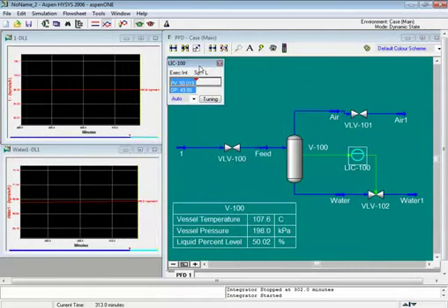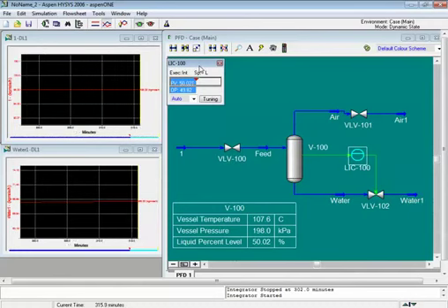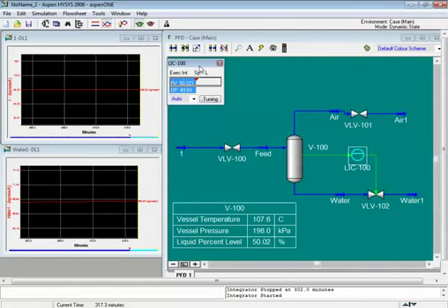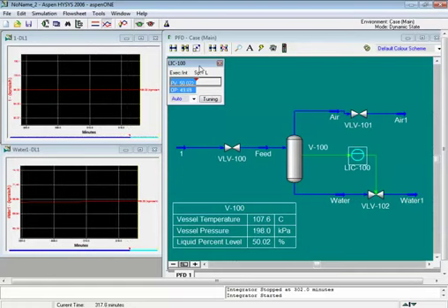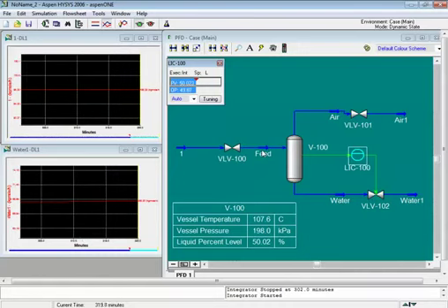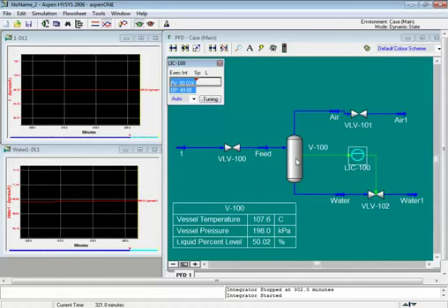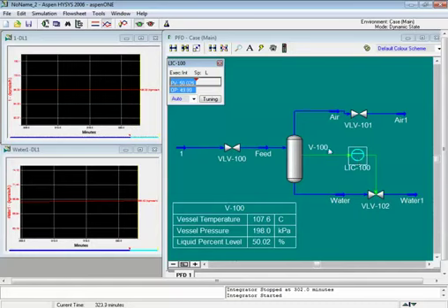To remember the basic fundamentals, flow can always go only from higher pressure to lower pressure. So in your steady state simulation, whatever you made, make sure that in dynamic simulation mode this pressure should be higher than this pressure. Then only will flow occur, otherwise it will give you a warning that pressure is occurring at negative side. Second, put the size of valves and equipment, and third is to put the controller at the right place with the right Kc and Ti.